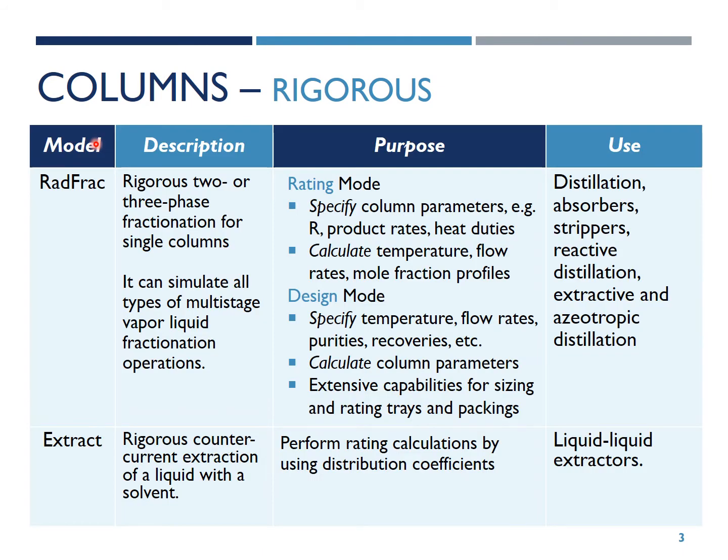The next model is RadFrac. RadFrac is a rigorous model for simulating all types of multi-stage vapor-liquid fractionation operations. In addition to ordinary distillation, it can simulate absorption, reboiled absorption, stripping, reboiled stripping, reactive distillation, extractive and azeotropic distillation.